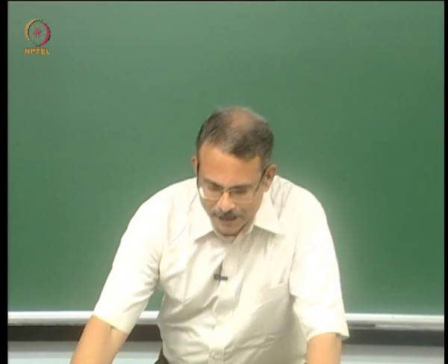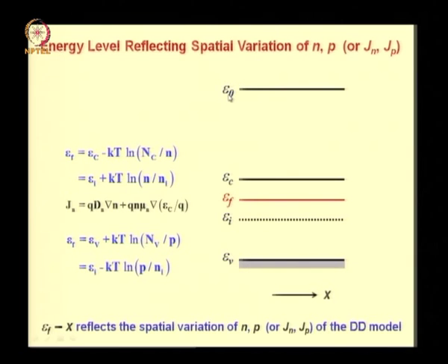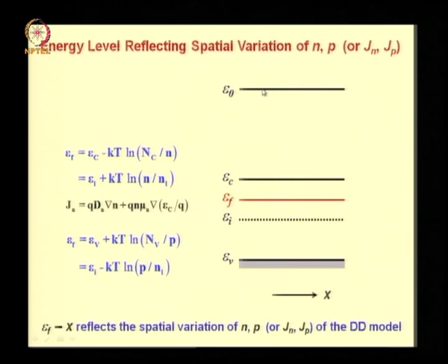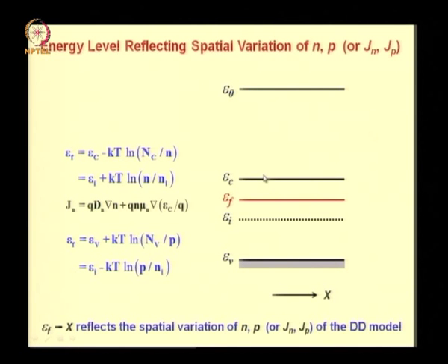The point is, the gradient of EC and the gradient of E naught are the same in this particular case, because this is a semiconductor whose atomic structure is not changing with distance, and therefore even if you were to replace EC by q with E naught by q, your electric field would have been the same.